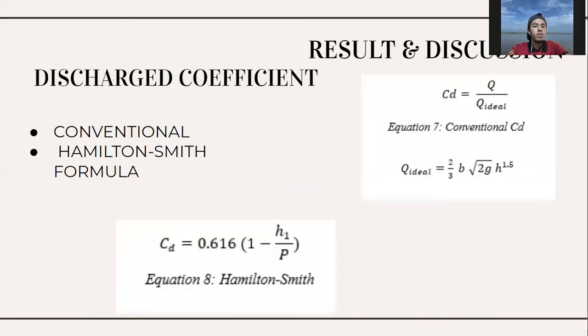Last but not least, for the part of analyzing, another parameter, the discharge coefficient, was determined. The discharge coefficient, or Cd, is the ratio of measured to theoretical discharge. It is related to steady flow with the same shape. The rectangular inlet was selected to prove the theory.